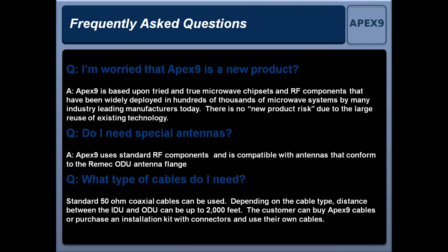And then the final question people ask is, do I need any special or crazy cables? In our case, we just use standard 50-ohm coaxial cable, so anything like LMR 400 that a lot of people have used and deployed before will work fine on our platform.